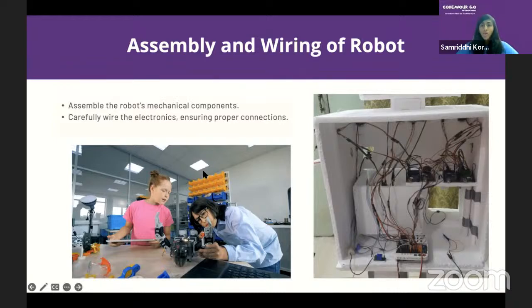So that time when it's all color coded, sensors a different colored wire and these two positive, negative, so that you don't interchange them, short circuit them, or it's just easier to wire and it's a convention which you can follow. And if you have a mentor and you send a picture to your mentor and he'll be able to assist you based on the color code. So these are a few tips I can give you. And if you can, of course, solder the wires. That's one of the best tips I can give you. And yeah, this is about assembly and wiring of the robot.